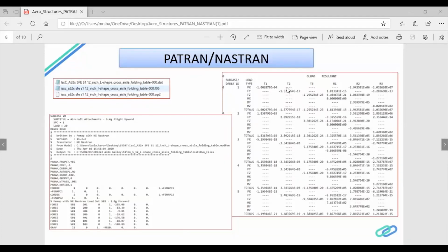Primarily, Nastran prints all the force resultants, the boundary conditions, and the elemental forces. This is also readable with any notepad or wordpad. So if somebody wants to write a macro that could import the result directly into an Excel file, it gives the user flexibility to do it.